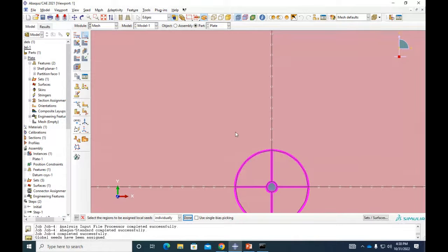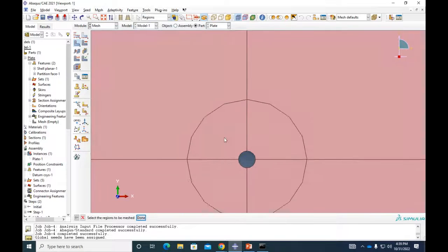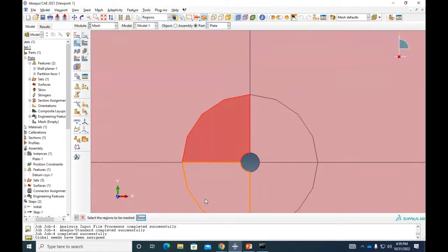Let's mesh one small region just to check if this mesh is actually gonna make sense or not. So for that, I hold this icon in here, and I'm gonna select this one that says mesh region. That is used to do incremental meshing, so small parts by parts. So Abaqus doesn't have the whole control of the meshing part. So let's mesh this one and then see what we get in here, all right? Let's see. It's gonna take a while because it's a lot of elements. Actually, maybe too much. Maybe I have to decrease it a little bit.